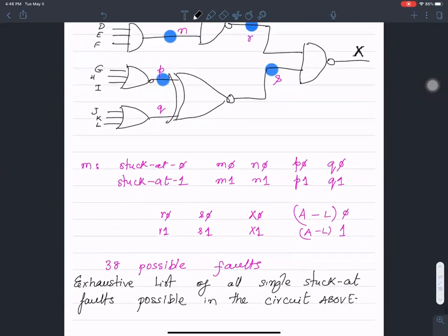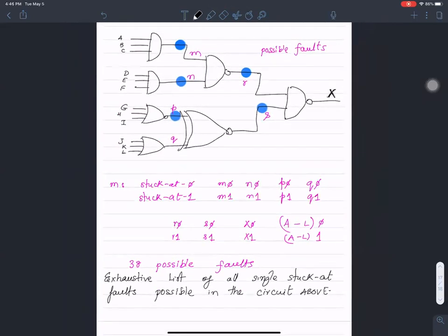Alberto had the question, if R and S are the same nodes, they're the same nodes. I fixed that. So in an attempt to outperform the brute force approach, I am relying on the notion of stuck-at fault, or fault modeling, which looks at each node and tries to eliminate if there's a stuck at 0 or a stuck at 1 at each of those, right? So that's the idea of stuck-at fault modeling.